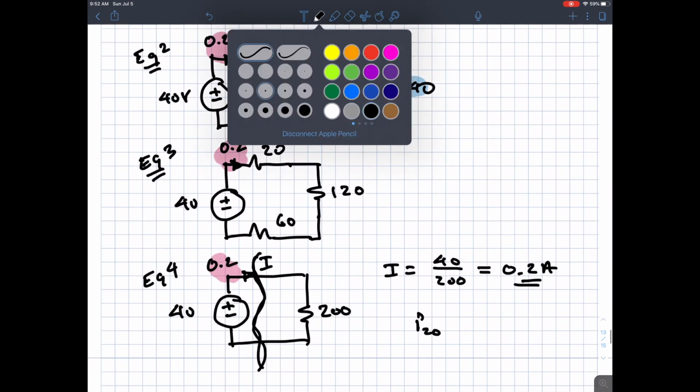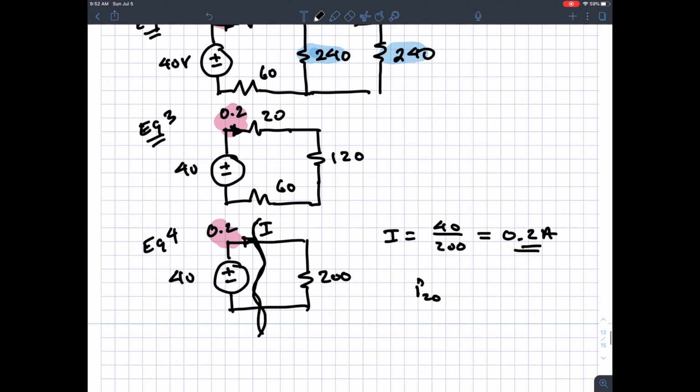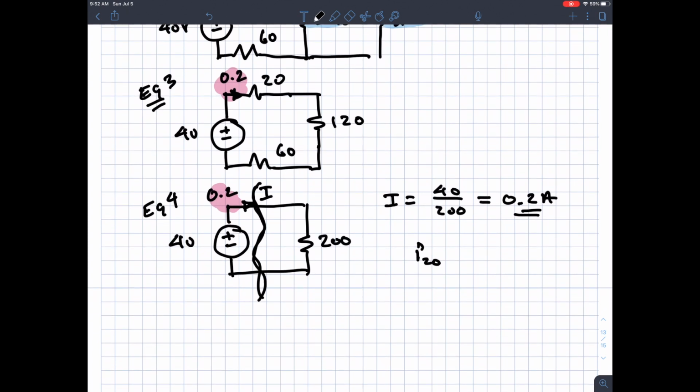It turns out there are a couple of formulas for power used by a resistance. I'm going to cover those now. Power is V times I. But for a resistor we have Ohm's law: V equals I times R. Then I multiply by I, and now we get I squared times R. That's one formula for power.